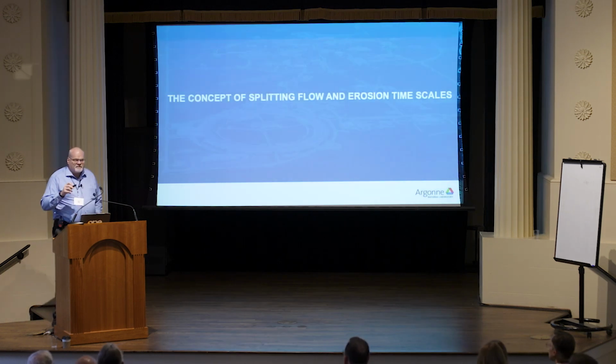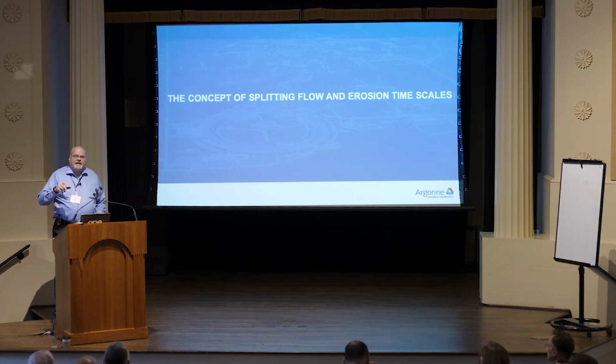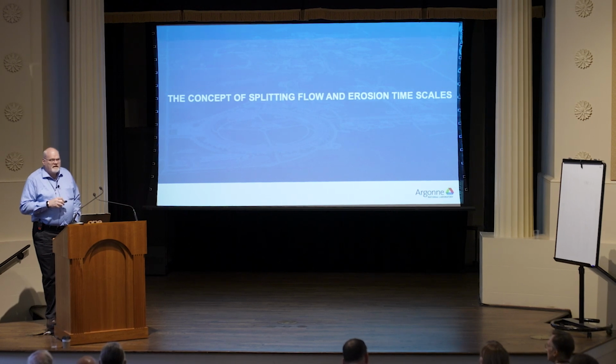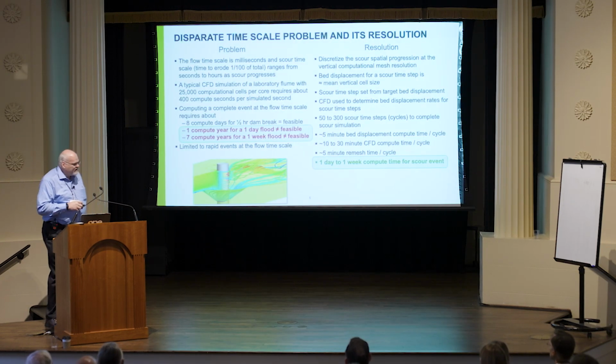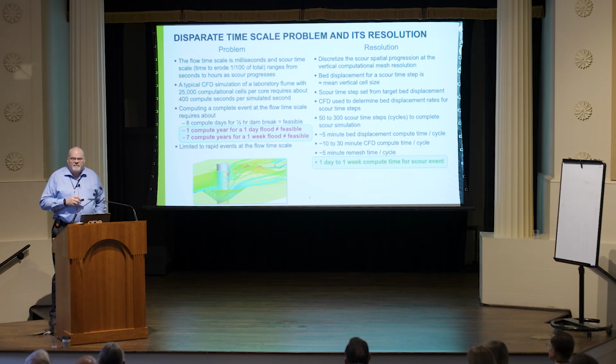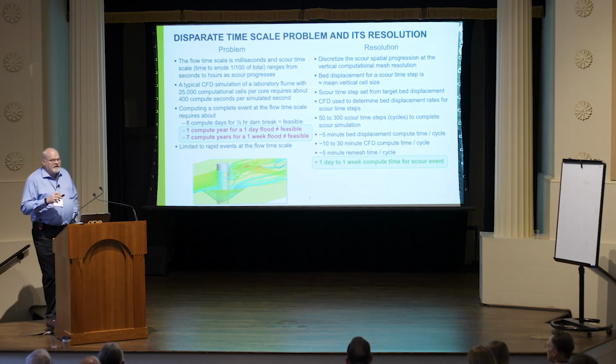So one of the problems with Scour is that physically, the processes that started, they happen very fast based on flow patterns, right? But then the erosion itself takes a long time. And the later you get in your case, the bigger the time steps. So things change slower later on, right? So if you just run a CFD case and you want to model the riverbed within that CFD case, then you very easily run into computation times of, let's say, 10 years or something like that, right? I mean, if you estimate how long it would take to run something purely as a CFD case and not use some kind of a trick to accelerate the process, right?